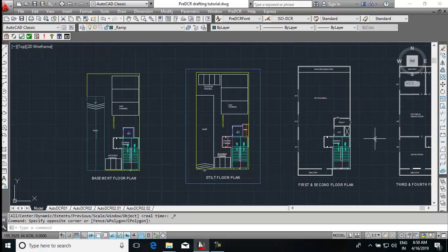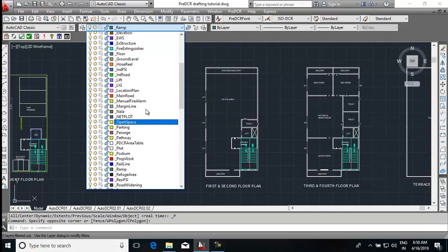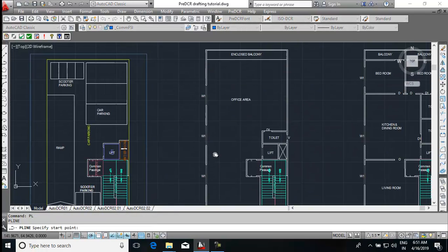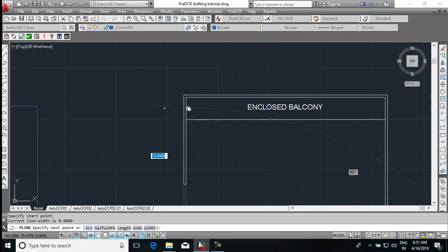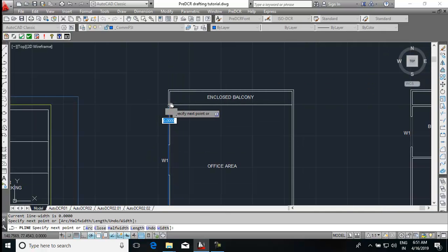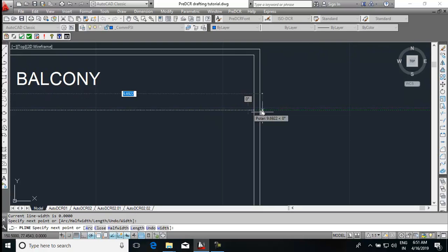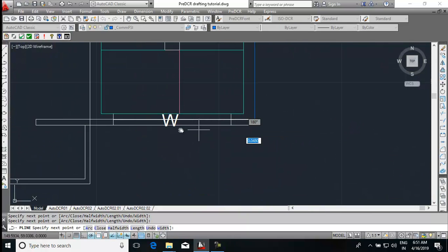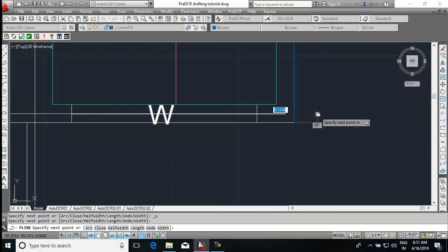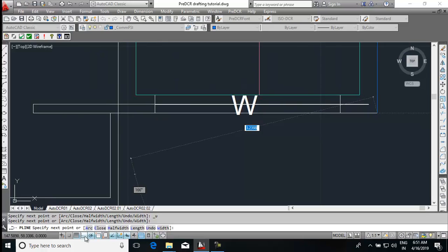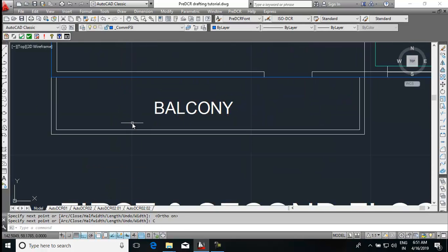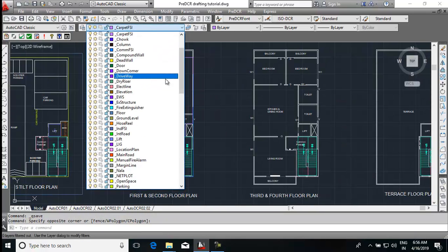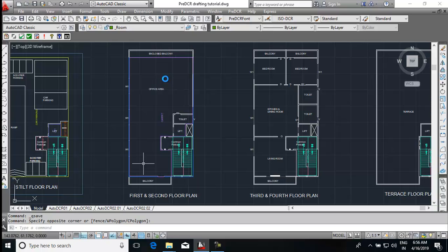Let's convert the first floor plan. For commercial floor, select COM FSI layer. Draw a closed FSI polyline which is used for commercial purpose. Room layer. Draw a closed polyline for each room as shown.